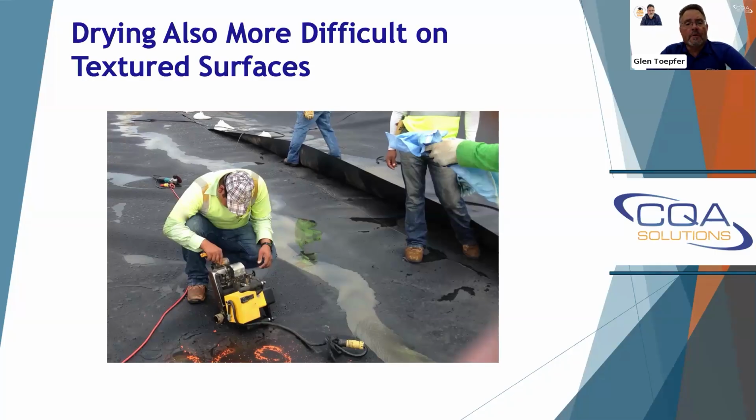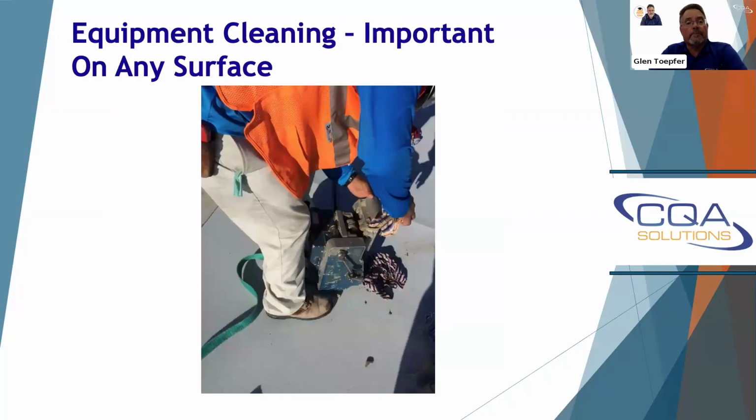And then, another thing you're always going to want to keep an eye on is whether they are cleaning the machine. After every seam, they should be taking a brush to the contour rulers and making sure things are clean, that the dirt's out of there, the nip rollers too. And if you don't see them doing that, a lot of times you'll see it results in failures that could have been avoided. I've seen it more than once where they don't take the time to clean.